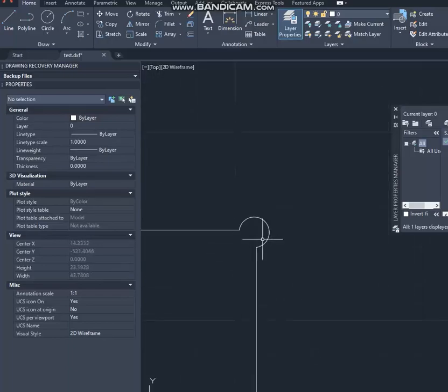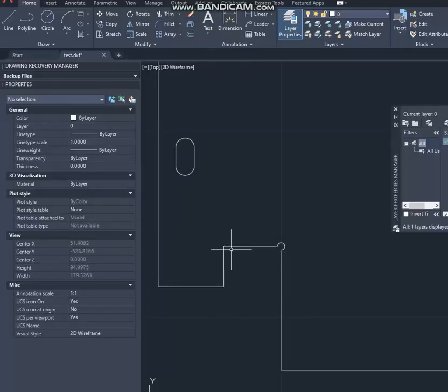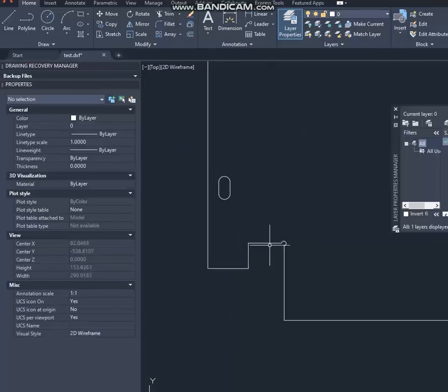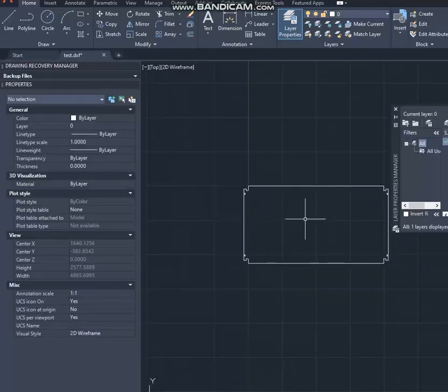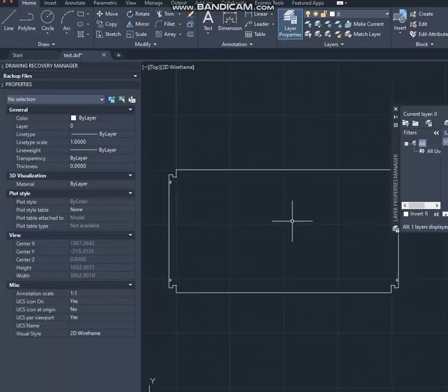So in these corners you will make this angle because apparently there will be a picture of cracks in the metal if you bend it under this straight angle. So yes, this is the entire drawing for the rectangular standard panel.